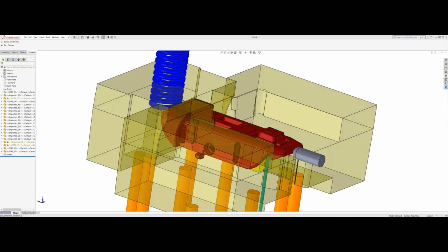But if you're running more production, higher volume parts, 500,000 plus, you do want to look at getting pre-colored materials. It's just going to be better overall, and it'd probably be cheaper at that point. You're just going to get better lot to lot and part to part consistency.